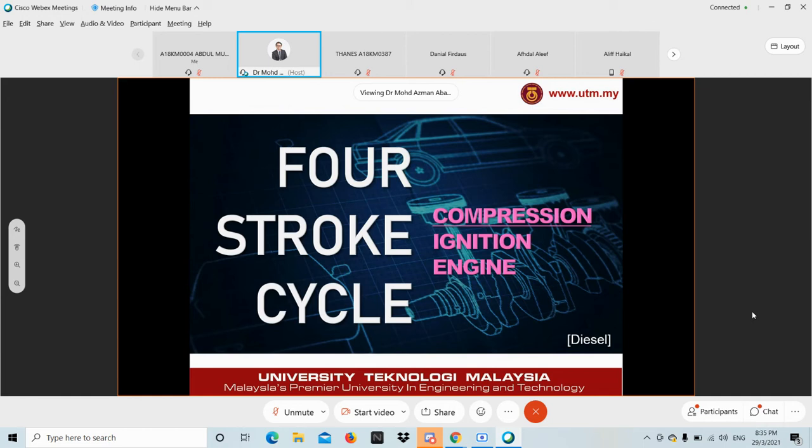Why do I say that? Because if you have an engine that is supposed to run on 95, it should be no problem, theoretically, for it to run on RON 97. But if the vehicle is purposely developed for a higher RON, 97 for example, then it will be an issue for the vehicle to run at a lower RON, 95 for example.